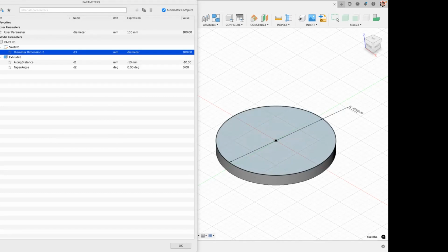So we come back down to our 75. We click once on that, and we start to type diameter, D-I-A. It's the only one in the list. It found it. Go ahead and hit once to accept it and once to apply it. I've got diameter written in.